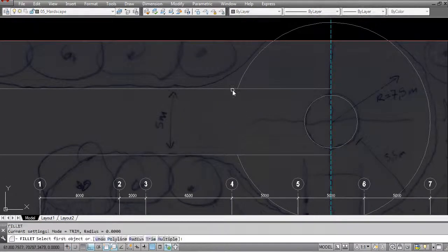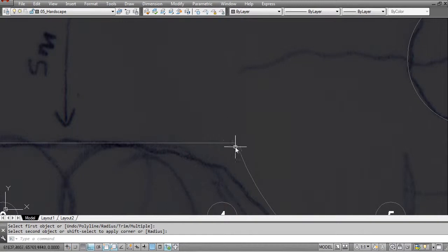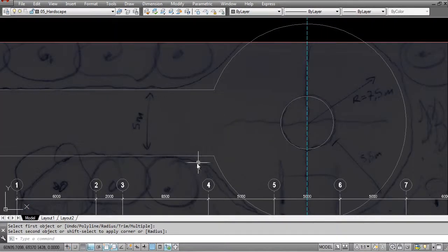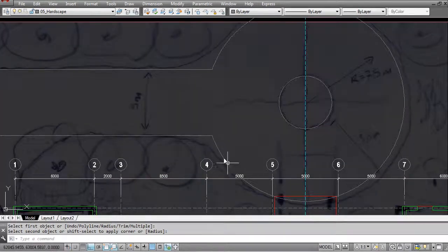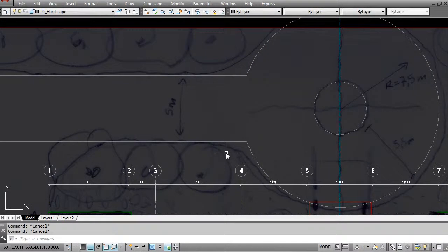But if you just fillet normally, you're going to get a pretty sharp angle as the two intersect each other and cut off the other overlapping edges. So to get that nice clean filleted curve, we want to add a radius to that fillet. So type F, enter for your ordinary fillet function, and here you see you have a radius of 0. So instead we're going to type R, enter, or otherwise click on that radius button, and you can now type in a manual amount.